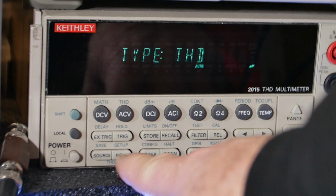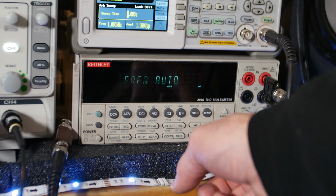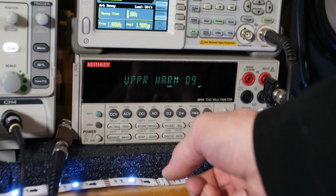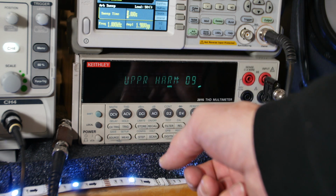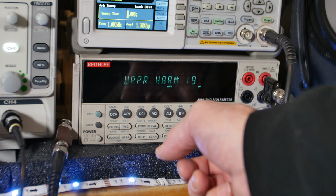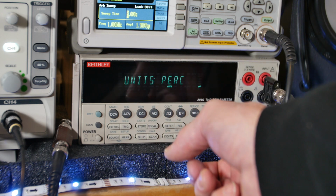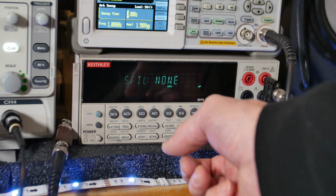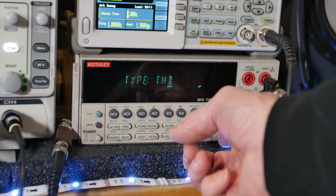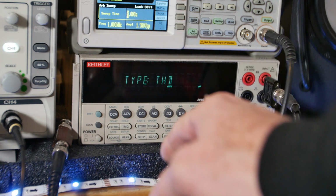When I hit this measure button, it says THD, and the frequency is auto. I've got up to 9 harmonics. I can even do more than that. I'll go 19, though I don't think it's really going to matter. I hit enter on that, and then we're going to show percentage. There are some other settings here: standard deviation, THD plus noise.